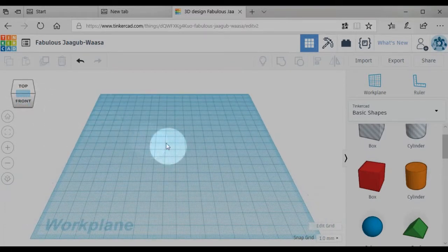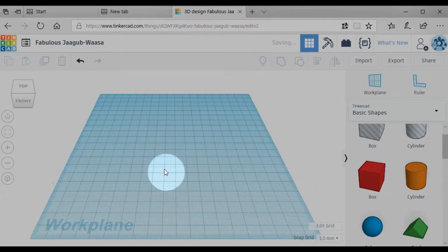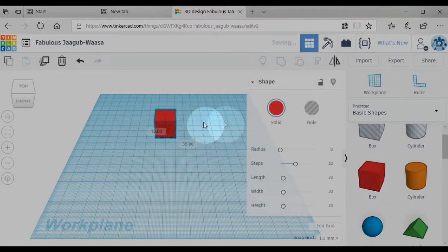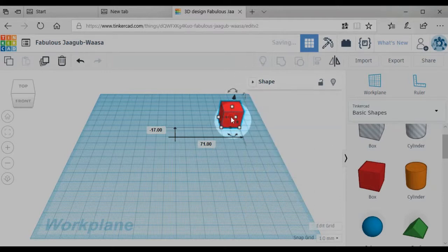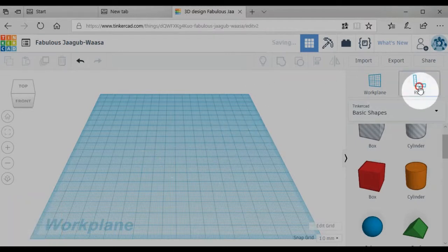When objects are created, they must be manually placed somewhere as the first step. There is one final note before starting the actual tutorial. The way that objects are positioned varies from program to program and should not be taken for granted. In Tinkercad, the build platform is the vertical center, but there is no horizontal center by default. As objects are repositioned, they are oriented relative to where they were just a moment ago. There is an optional ruler that may be placed on the build platform. The ruler establishes a horizontal center and simplifies explicit positioning.